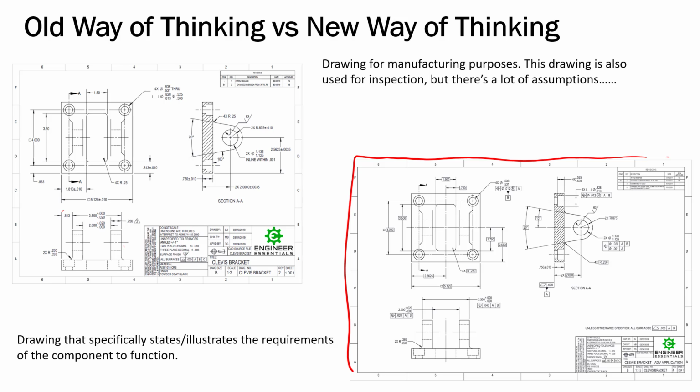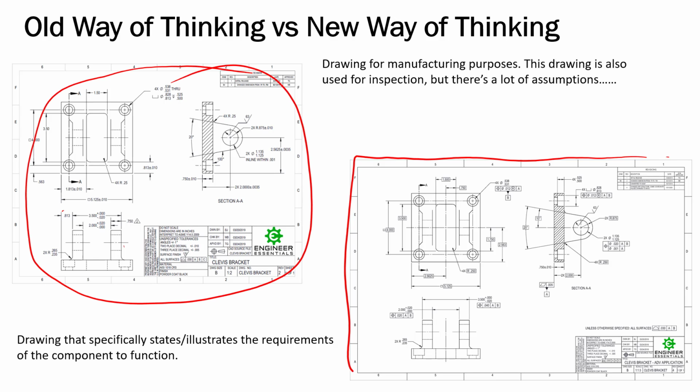So they'll just do the best they can. They're kind of taking this approach to it: they're just going to come off of a surface because they don't understand the datums and give you the best thing they can give you. So you may wind up with bad parts, and that's another result of this.